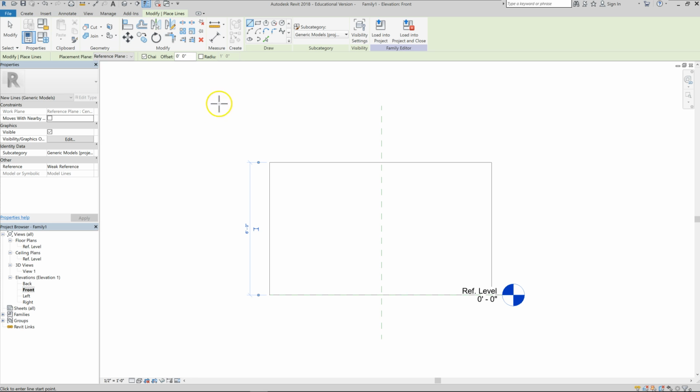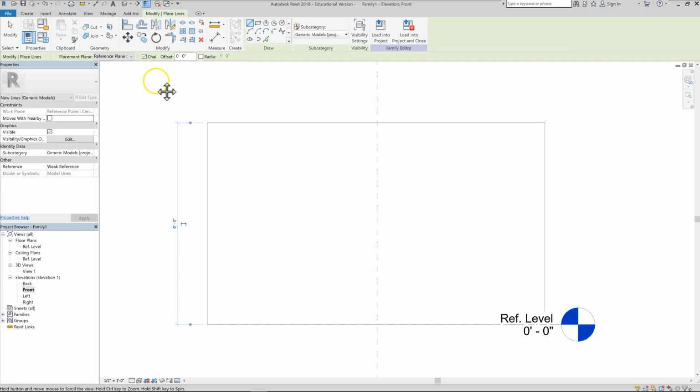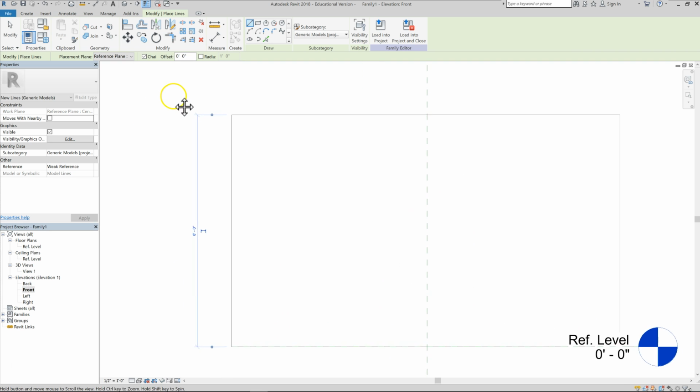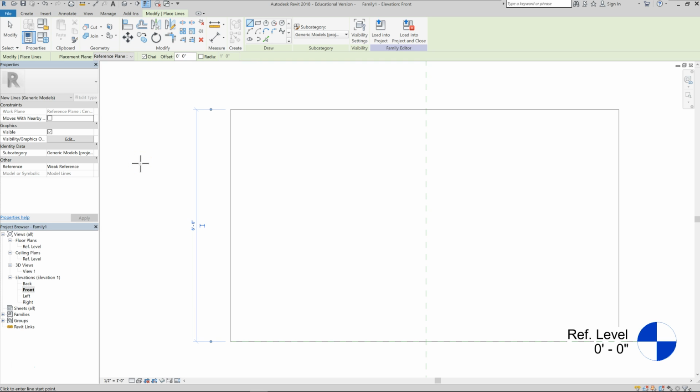All right, next thing we're going to do is offset for our material thickness. This is the outer shell of our shelving unit, so we're going to offset to account for our material thickness. Depending on the material that you have chosen, you need to know the thickness of that material. I have chosen to use a 3/4 inch multiply plywood to build my shelves, or at least this portion of my shelves with. So I'm going to offset 3/4 inch.